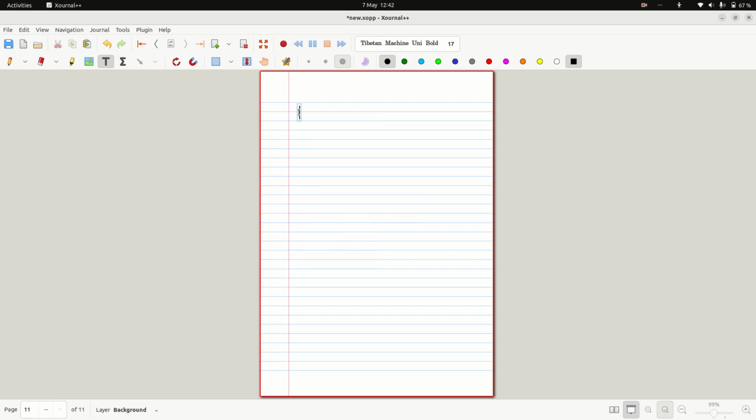Here I am going to write some code. This code is written for toggling an LED. Initially we need to write #define LED1. Here I am going to use port D. I am going to use a single LED, so I am going to write RD0. Next is the main function.